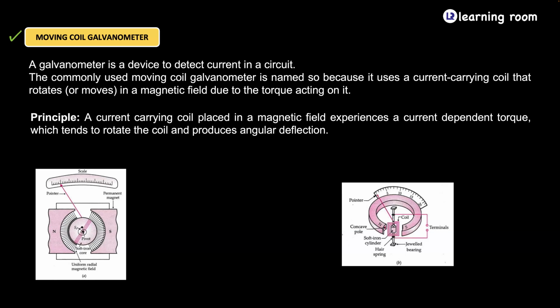See, I'll take the positive wire and place it into this positive terminal. I'll take the negative and place it in the negative. Are you able to see some deflection here? It has got deflected completely to the right. Now, if I reverse the polarities, what will happen? The deflection is to the left. So this is one preliminary check that you can do to the galvanometer that is given to you.